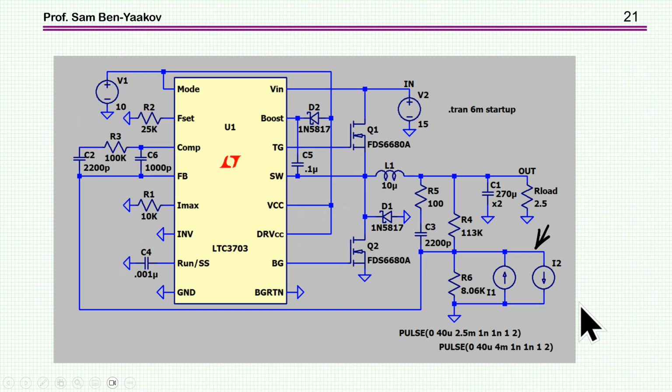So now I'm exposing this system to a step. Now I cannot go into the reference, of course. So what I'm doing, I'm injecting here a current into this junction, which of course goes into the feedback into this amplifier here, the error amplifier. And I have two sources. I have one which is injecting a positive current, meaning the voltage will go up, so therefore the output will go down. And then we have the other polarity too. So this is just to see the response, you might say, to a reference.